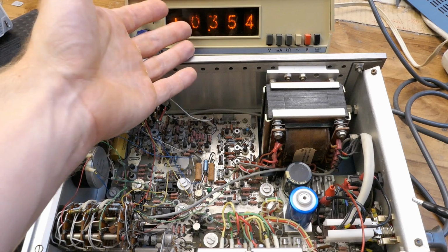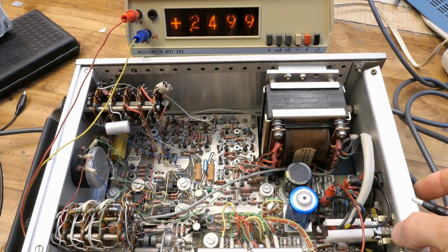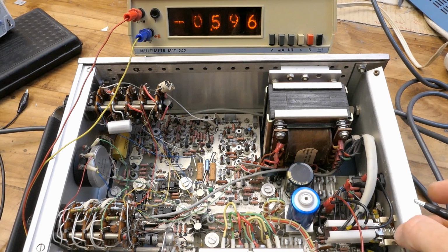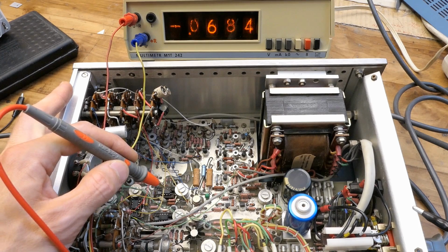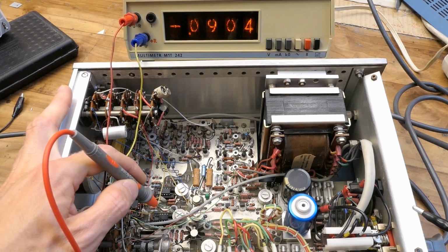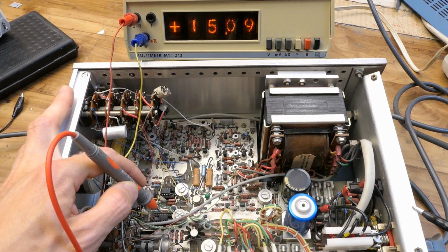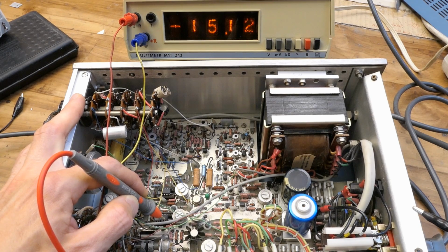And using my old multimeter, let's check the voltages in this thing. It has a symmetrical power supply, and the positive rail before the regulation is about 24 point something volts. And the negative rail before the regulation, again 24 point something minus. And of course typically OpAmps are using a symmetrical voltage plus and minus 15 volts. Let's check it on these 741 OpAmps. The pin 7 is the positive, I guess. 15.09, nice. And the 4th pin is the negative, I guess. 15 point something again. This seems right.